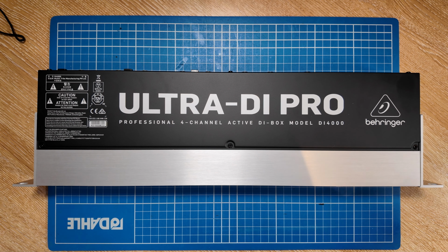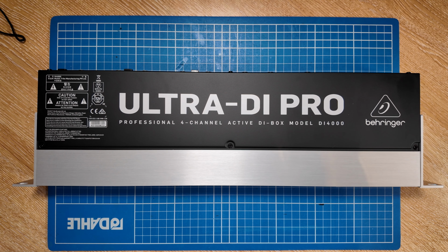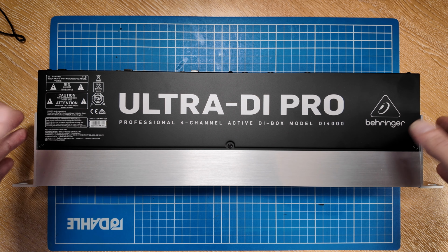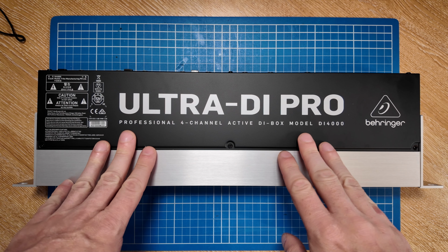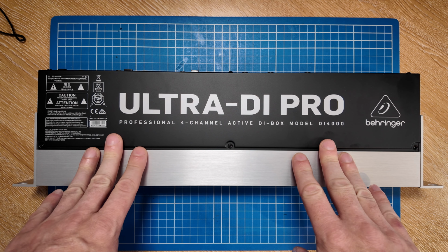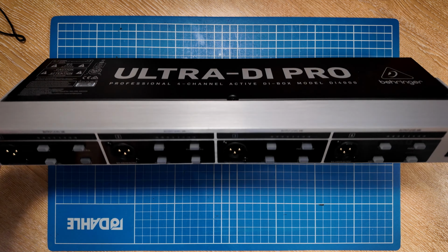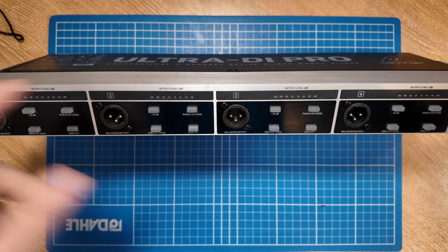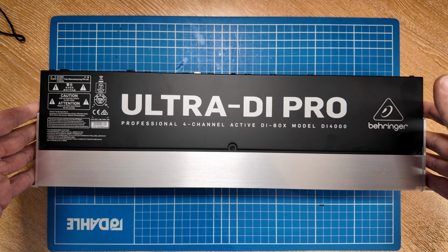Now, there are lots of different DI boxes out there. They're very similar to a line isolator in the way that they work, but they specifically provide impedance matching, and the one that we're going to take a look at here also allows me to take a speaker output and feed it into a line in on the mixer without any danger of damaging it. So this one is the Ultra DI Pro, the DI, I think it's the 4800 from Behringer. It's actually 4 DI boxes in the one chassis, which provides all the connections that we need.